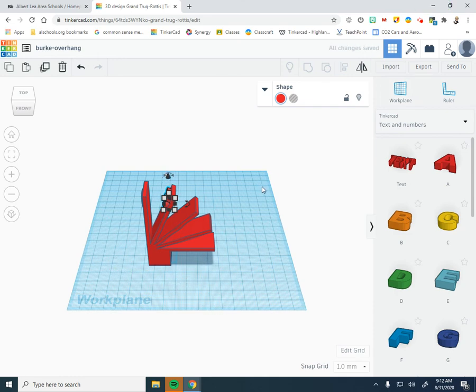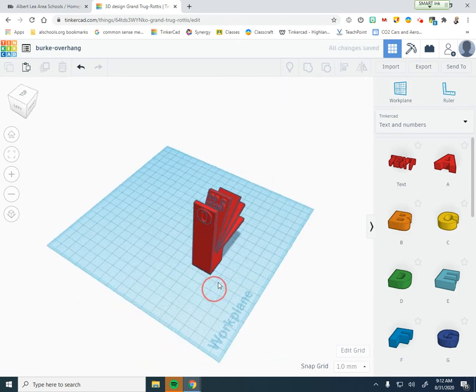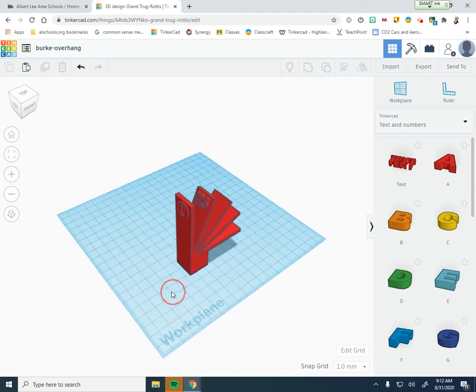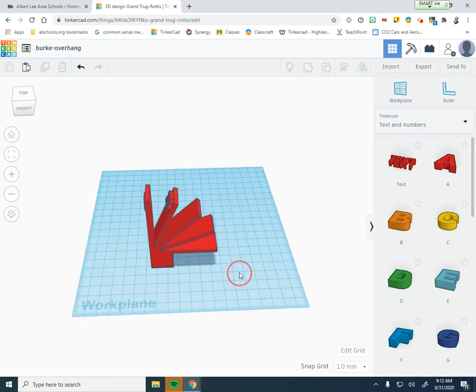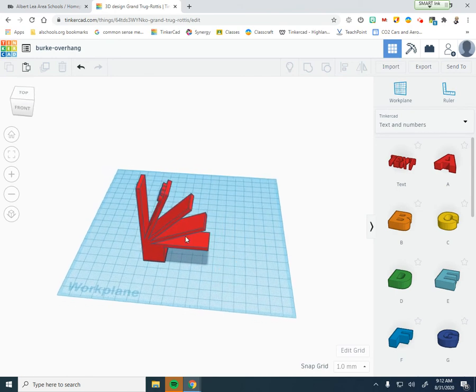Then we'll click off of this and you see here, I've got my 0, 22.5. You would continue to mark this 45, 67.5, 90. When you are done, you're going to go through and get all of those set up. You're going to make sure that you have all of your models oriented and everything is set. Then you're going to have to export this and save this as an STL file to be submitted for printing.